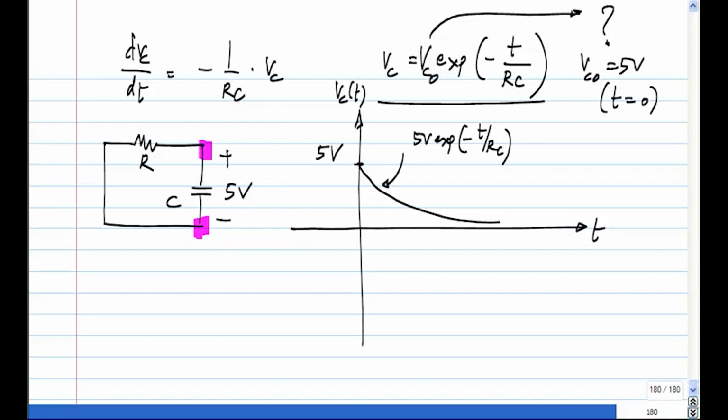That's known as asymptotically reaching some value. That is, it won't reach that 0 value for any finite value of t, but only for t equal to infinity. So you should know both these: how to solve for this, which is after all a very simple equation, and at the same time why it comes out the way it is, that you know from the circuit that the current in the capacitor keeps on falling.